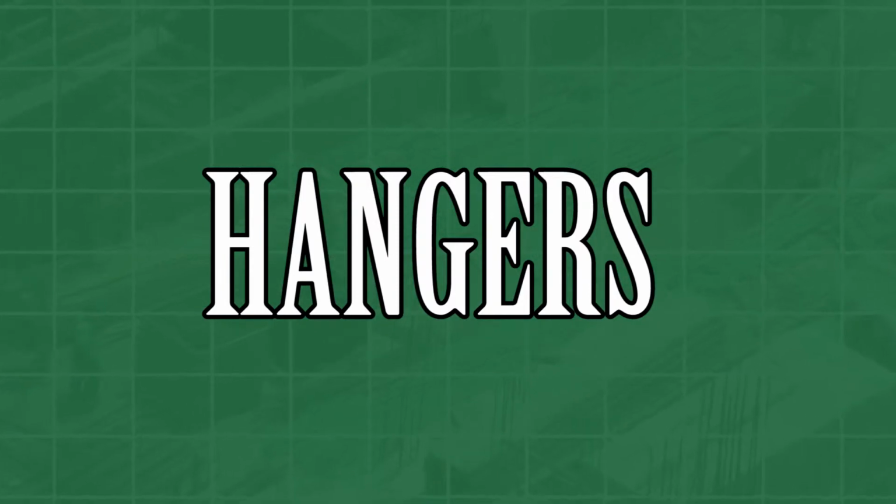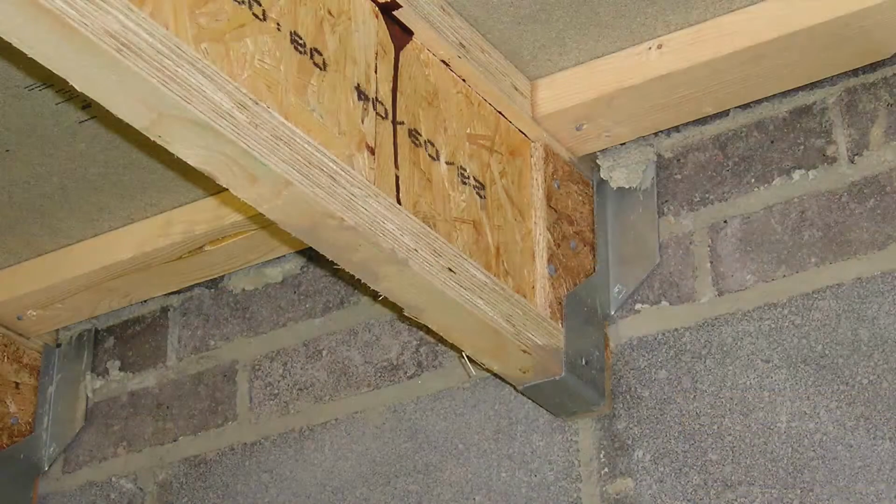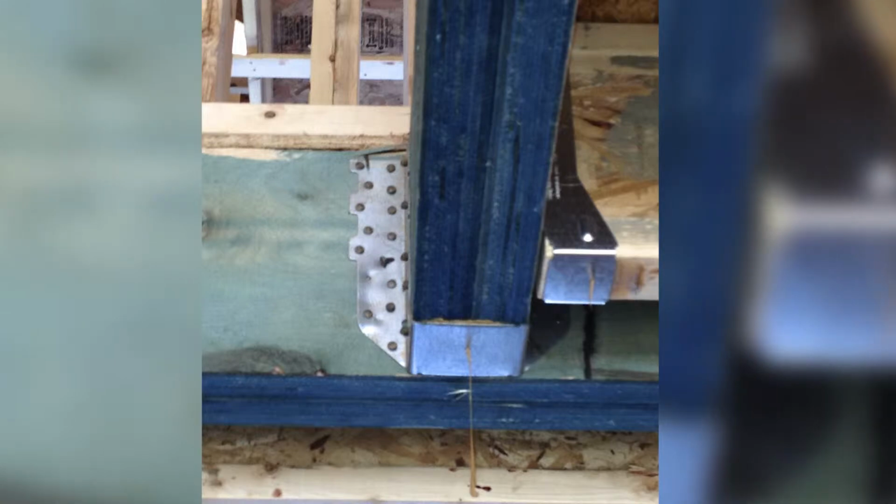Hangers. Hangers are metal supports that hold a joist in place. Joist hangers vary in shapes and sizes depending on the number of joists or beams being placed in them. They mainly consist of three types, which are shear hangers, post frame hangers, and heavy-duty shear hangers. They can be hook-up or non-hook-up.